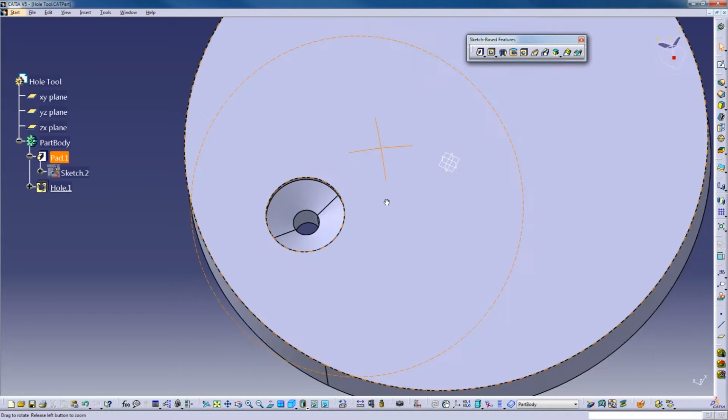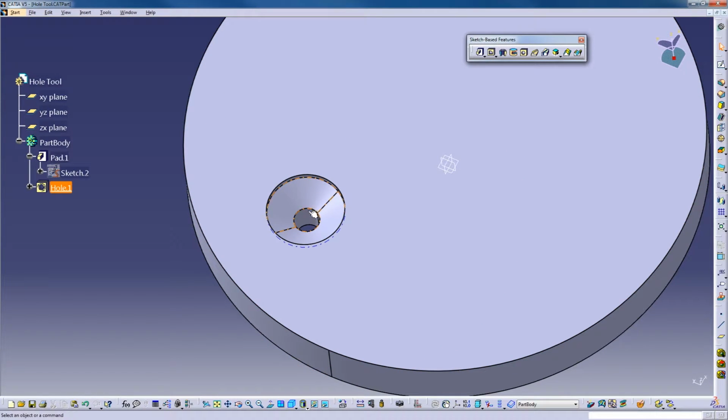I like the idea that you can make the holes in CATIA and then make them on the mill rather than a drill, because drills tend to come in certain sizes, like what I just said. An M5 fastener will say use a 4.5 drill to make the hole and then tap that.